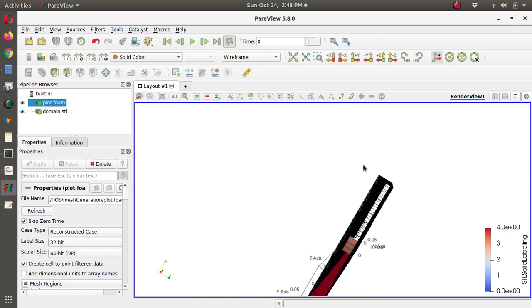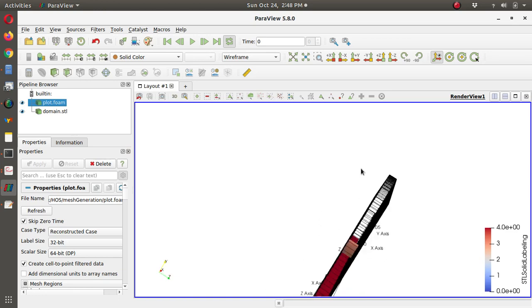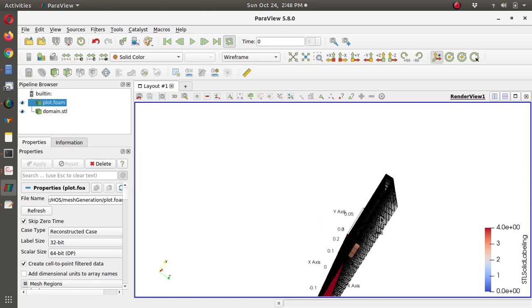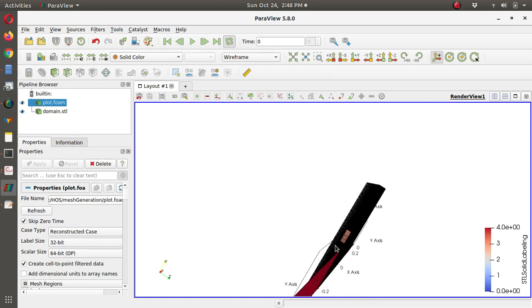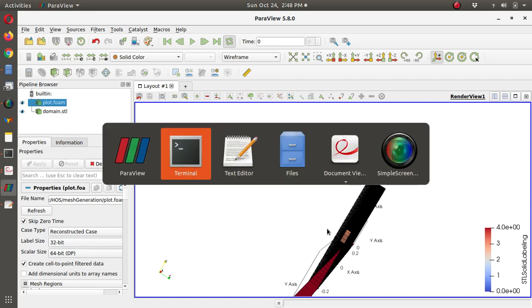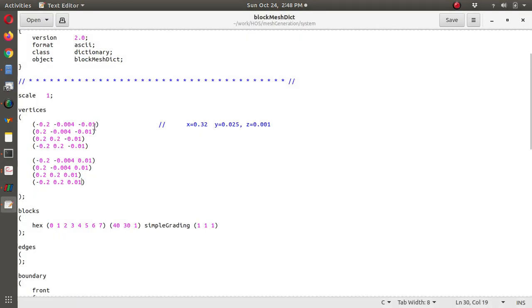You can see this has gone closer, right? The front face and the back face become closer to each other. I want to make them closer still, so again I am going to reduce the values. I am reducing like this, just putting one more 0 in the values, because first I have to make the two-dimensional mesh. That's why I am doing all of this.